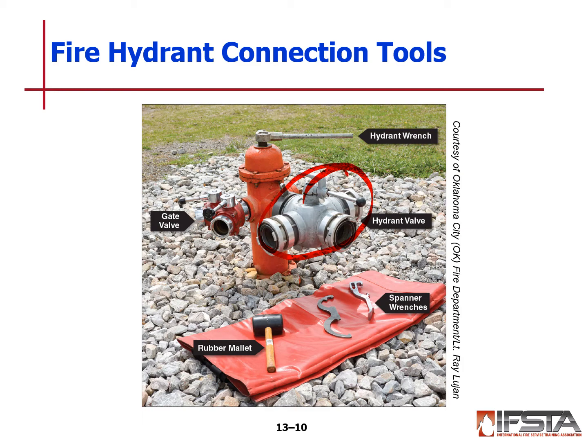Sometimes we'll put a gate valve on one of the hose sides there, as you see on the slide. This could be a Y, this could be just a straight valve. And we'll put that on there so that we can flow extra lines without shutting the fire hydrant completely down.